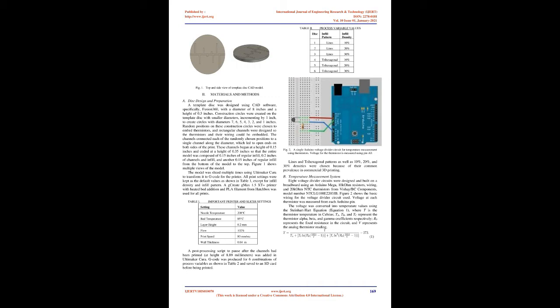Varying the infill density and the infill pattern has multiple advantages. For example, prints with higher densities tend to have higher tensile strength, and prints with more complex infill patterns tend to have higher compressive strength. Heat transfer in FFF. Within a printed object, conduction and convection allow heat to be transferred throughout the material.